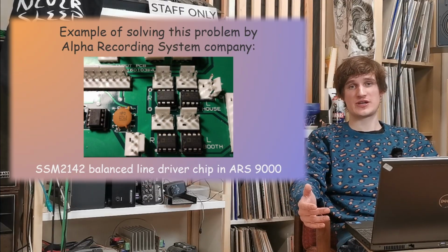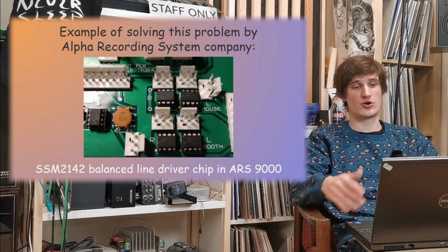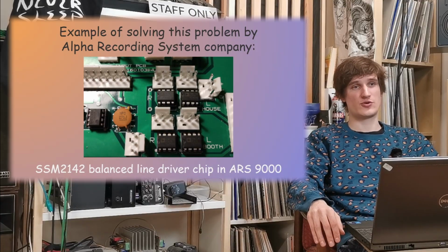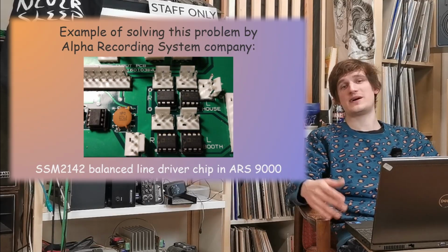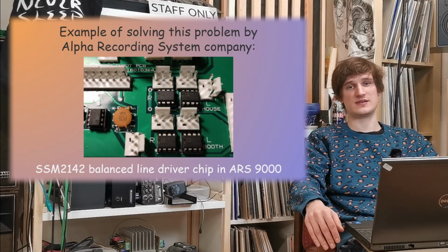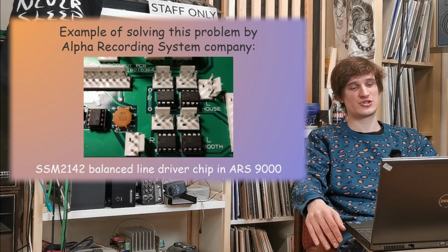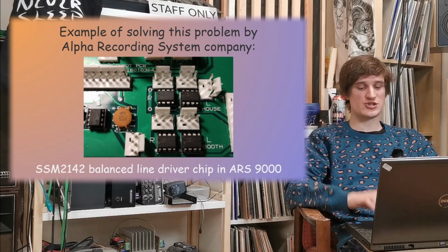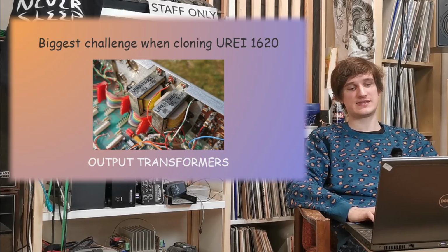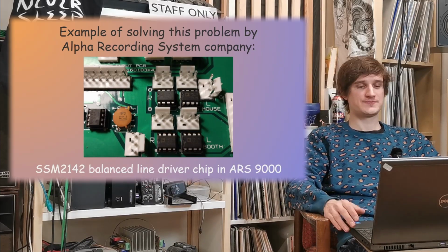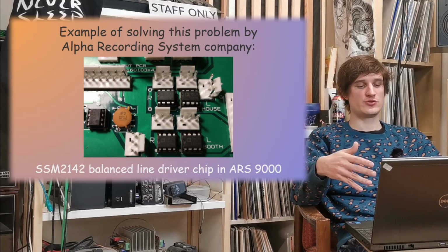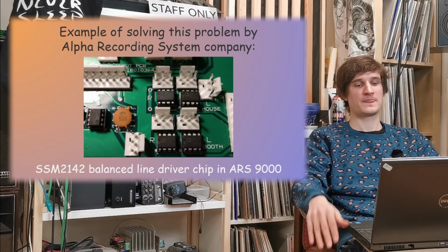People that were watching my video series saw those parts before. Those balanced line drivers were used, for example, in Master Sounds mixers. They used THAT Corporation chips. Here we can see chips by Analog Devices. So essentially what ARS did is that they replaced output transformers with active circuitry. They used just a balancing chip.